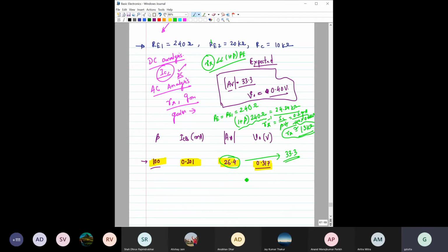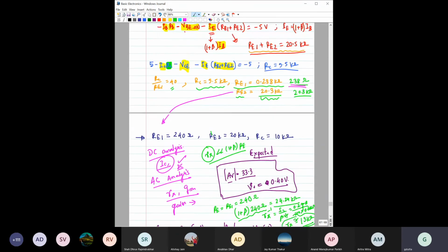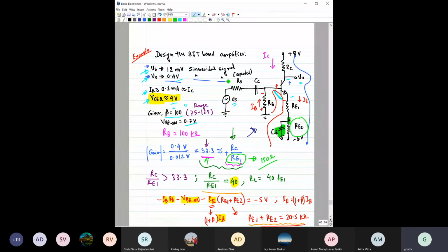And finally you can take one transistor in a simulator, this PSpice type of simulator. Using LT Spice, you can make basic circuits and simulate this circuit both in AC and DC, and find the total voltage here. Total voltage is the DC voltage plus the AC voltage, right? Then if you have a capacitor here, at the output you will only get the amplified AC output. The DC portion would be blocked, right?